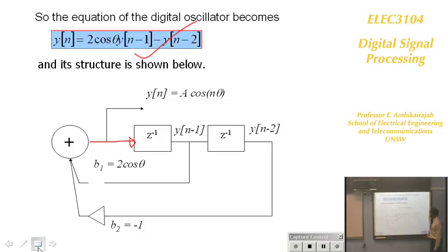Your lecture notes have it right. Now it's only wrong here. Well, it's just basically how we draw it. So this is an oscillator, right? There's no input here. Here's an input, Xn, right? And no input, so that. So where's the output there? Delayed by one sample, Yn minus 1, multiply that. Yn minus 2, multiply that. That's my oscillator. That's an output.